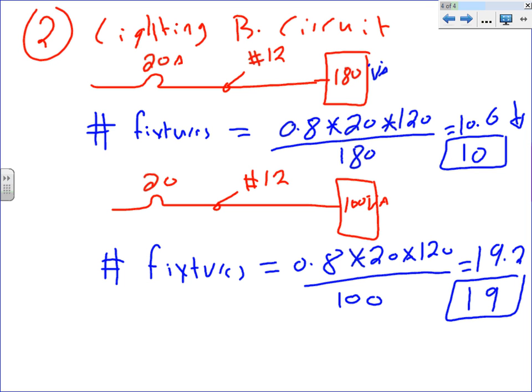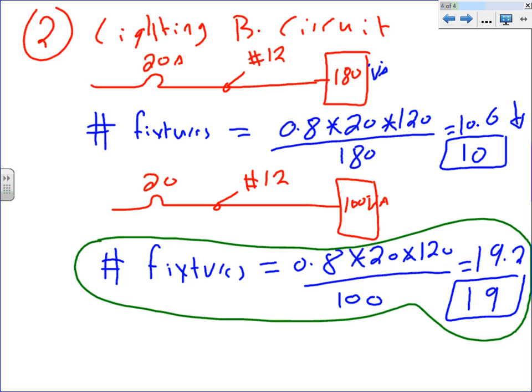Is that more in the ballpark? Yeah, more, like the 32 watt units. Absolutely. That's exactly based on the assumption of a fixture right above your head, and that's not a bad assumption, guys. The first one is the worst extreme scenario that you can encounter. To meet the energy code, I want to highlight that one; to meet the energy code, you almost are in here. So I'm going to highlight this one and keep it in your mind. This is how many fixtures you can put on the lighting. So can you use this one as your design criteria?